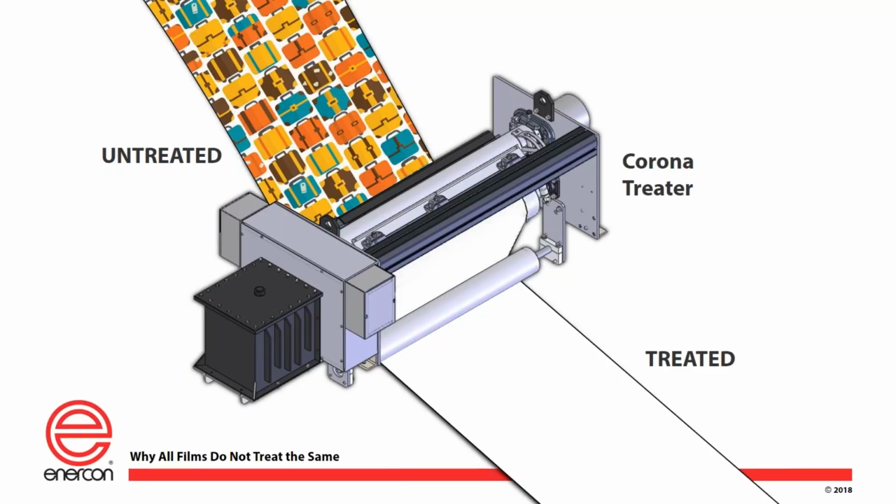So that's really what the treater is doing here. It's taking this film that's loaded full of these various things, and we're trying to correct for some of that as the film is surface treated. If we take, for example, a slip additive, which tends to be something people are very familiar with, and we have a lot of slip on that surface, after the treatment here we're going to try to print it. We need to get some of that slip off that surface, clean it up so that the ink has a fresh spot to land on, which would allow wetting and then allow adhesion.